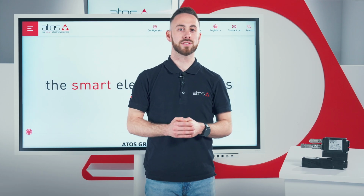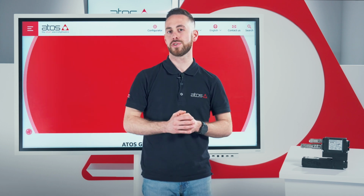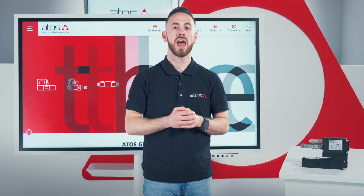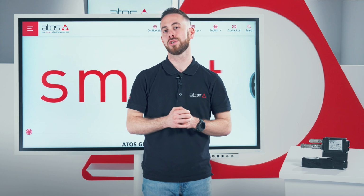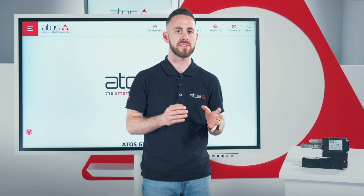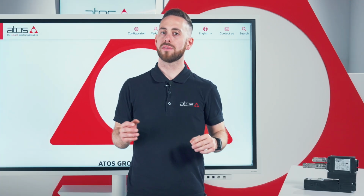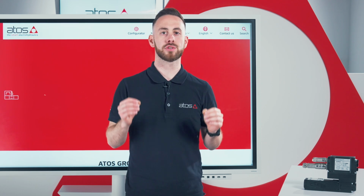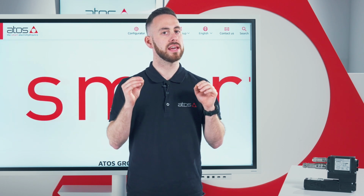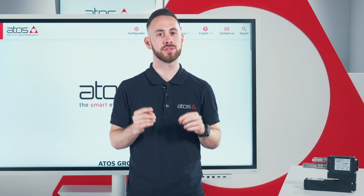Obviously, it always depends on your performance level requirement, but we strongly suggest a magnetostrictive transducer with digital SSI output, as this choice allows you to achieve higher position accuracy and save valuable time during the commissioning phase, avoiding several wiring optimization and fine-tuning operations on your system. However, the compatibility of the digital transducer with the Atos axis controller must always be carefully evaluated by our team of specialized technicians, who will be able to guide you toward the best